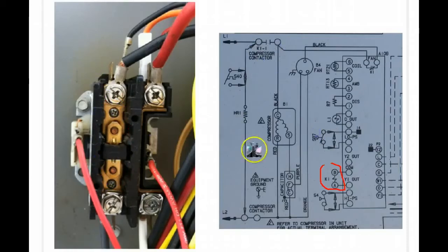And then it just so happens on this contactor there's a straight through bus bar, so this voltage is always applied through this bus bar. That's a straight through shot, and it's all the way down here at the bottom of the schematic symbol. So what we end up with is the coil is here, the normally open contact is here, and the straight through contact is here.